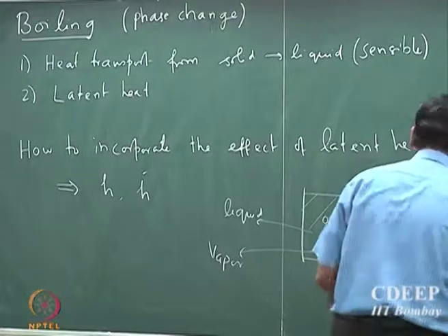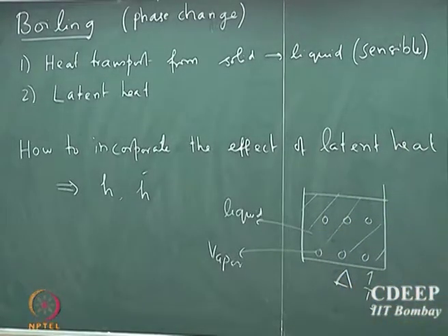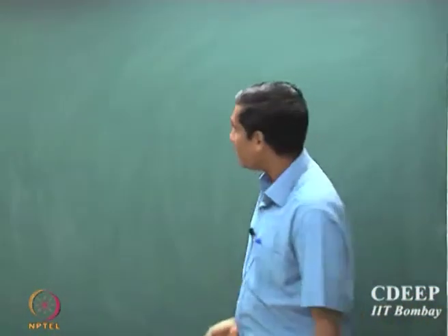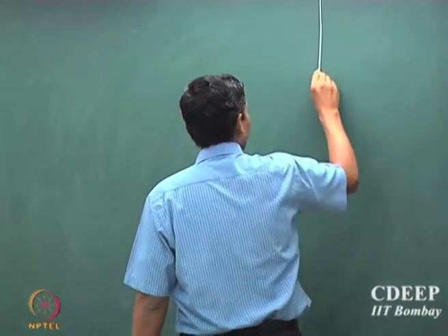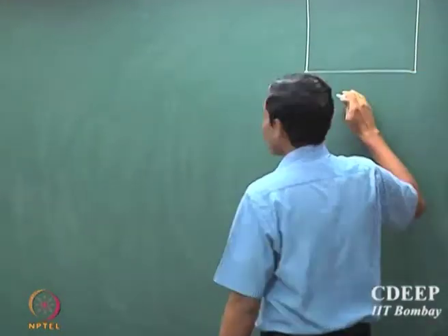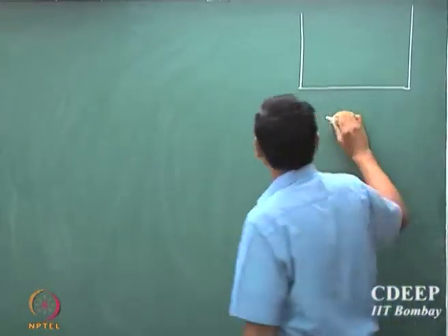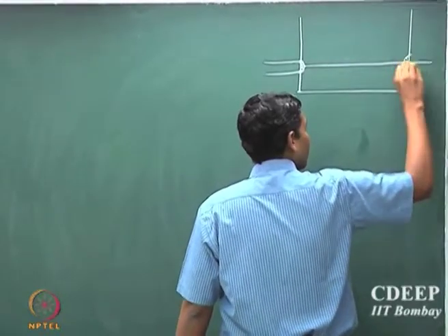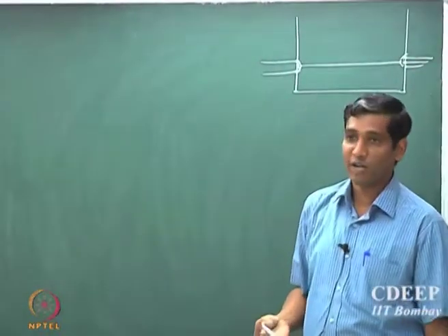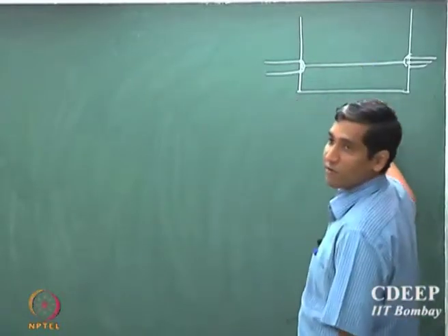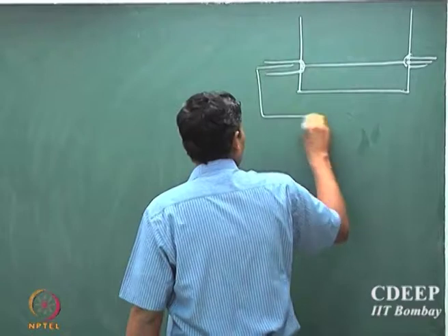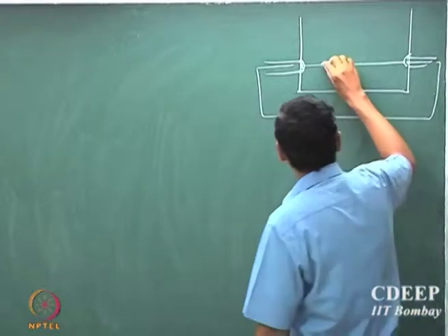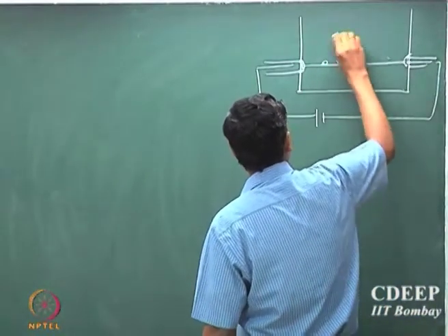So in order to do that, we need to first look at how to perform a controlled experiment. A controlled experiment was performed, and the way it was performed is, instead of heating from the bottom of the container, a platinum wire was placed inside at a specific location, just slightly above the bottom surface, and you electrically heat the platinum wire, and so you will start seeing vapors formed.